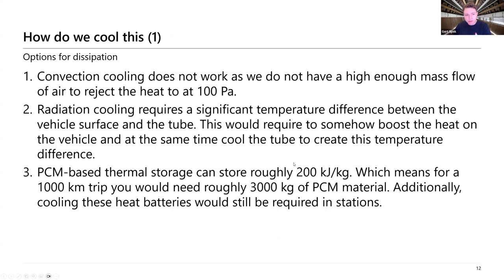for these kinds of applications is PCM, paraffin wax type thermal storage, which does around 200 kilojoules per kilogram. It's quite volumetrically efficient, so it should be quite doable to package that. However, you need another 10% of mass, assuming this already good case for a 1,000 kilometer trip, which would mean for a 2,000 kilometer trip, it doubles, of course, but also if the estimations on the drag are off by a factor 2, which they could very well be, that would also mean another doubling.